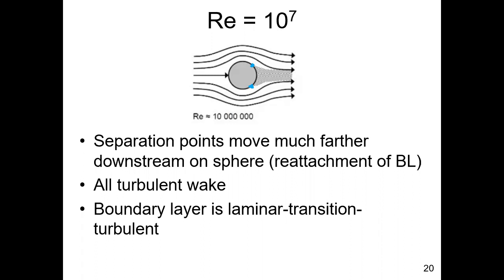Compare that to turbulent motion. In turbulence, you've got mass movements of fluid that can easily communicate there's a solid boundary. And so the turbulent boundary layer is much better at communicating this signal that there's a boundary down there. And that's why the boundary layer can reattach. It's capable of staying on the object for a much longer distance to make that communication. At this Reynolds number, there may be vortices, but it's really unstable. So you're well past the range where it's something that's predictable.